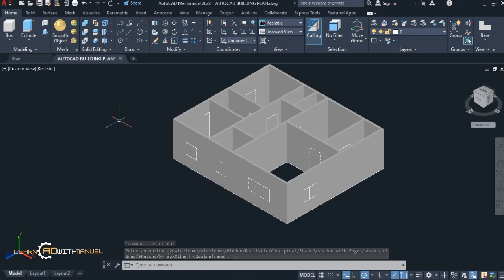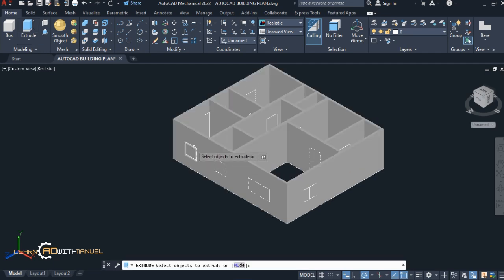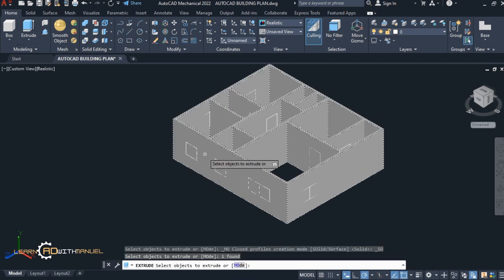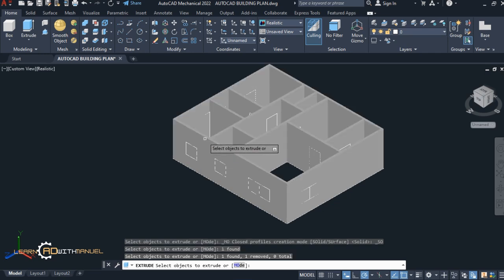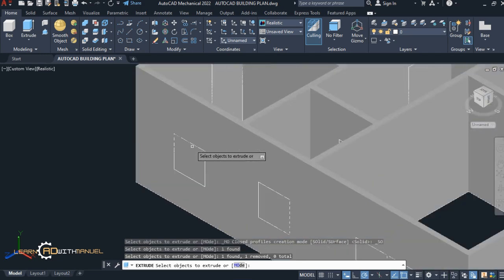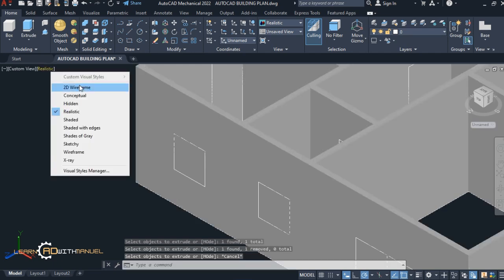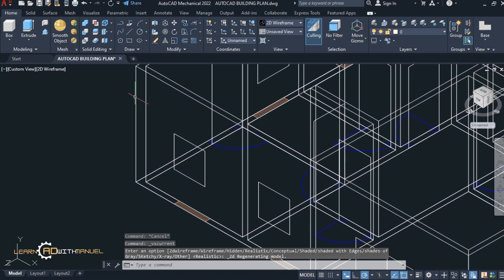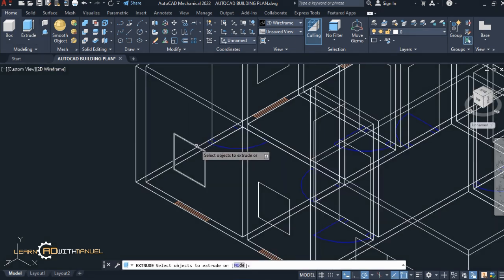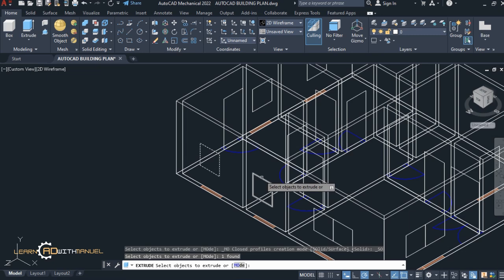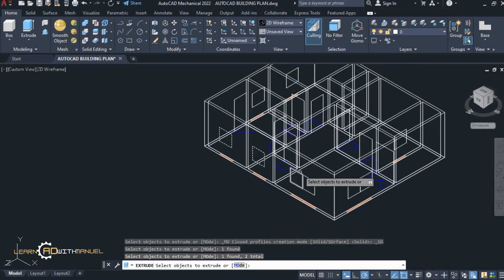So the next step here is we are going to extrude all the windows. Let's say we are going to select this window. Let's hold shift to deselect. Then let's carefully select all the windows. Shift to deselect. I think I know what I'm going to do. I'm going to come to tutorialFloor, so I can be able to select them carefully. So we come here, then we select this, then this and this, then enter, as you can see.